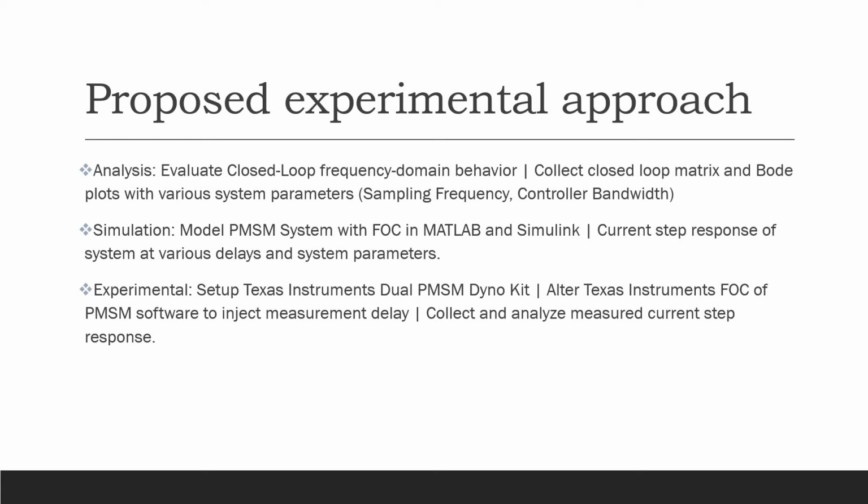And then to achieve and to analyze the results for this research, we need to alter the field-oriented control software to behave the way we want and to inject measurement delay into the system. And then from here, we will collect and analyze current step responses from the system and maybe a few other results.